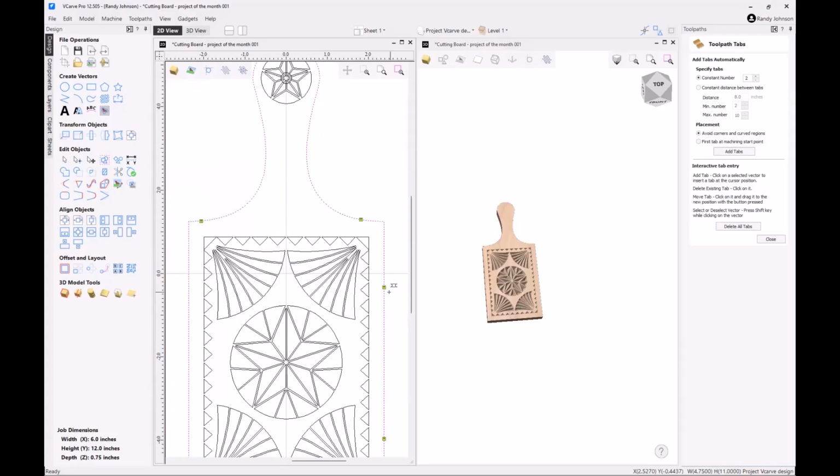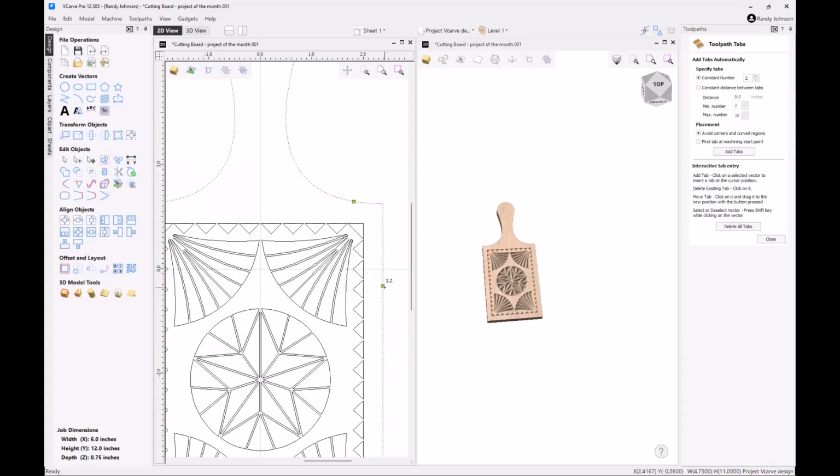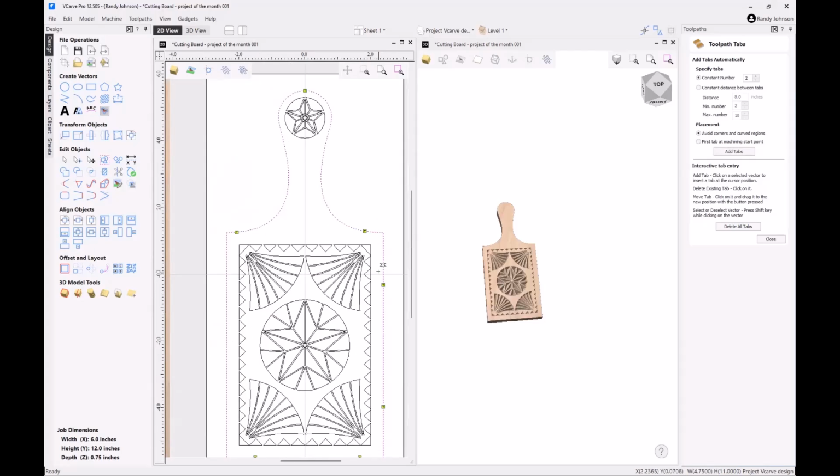The other issue is that sometimes these tabs, when you take the project out, it can chip out and actually chip into your project. I mean, both tabs can do that. So when you take them out, using something like a Japanese saw or a little back saw, or even the band saw works well, and then sand them down. Some projects out of MDF, you can get by with a chisel or a utility knife. You'll come up with some solution there, but you just want to be careful when you remove them not to chip out your project.